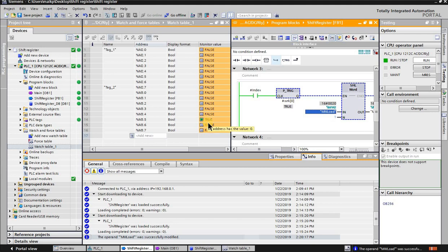It goes all the way through 3.7, 2.0 goes through here, and then after 2.7 it will just fall down. 2.7, boom, gone. So keep that in mind if you work with shift register, that words and bytes are a little bit differently structured, even though they come from the address right behind each other, but it's actually reversed. So keep that in mind.